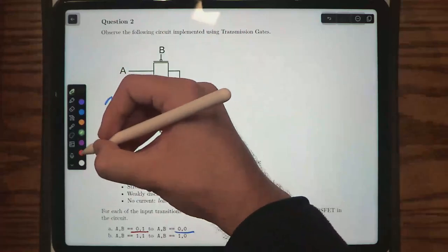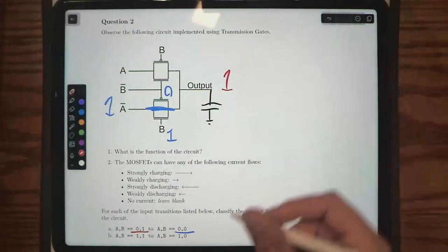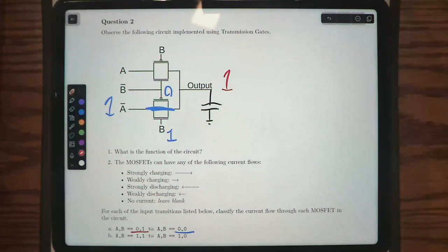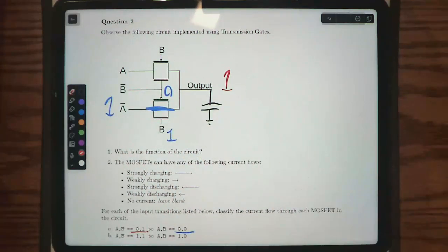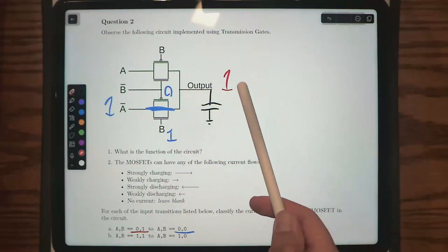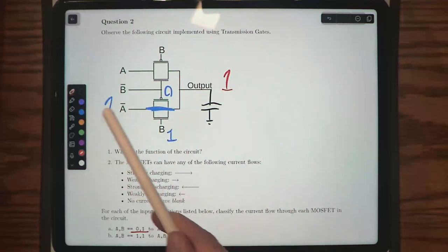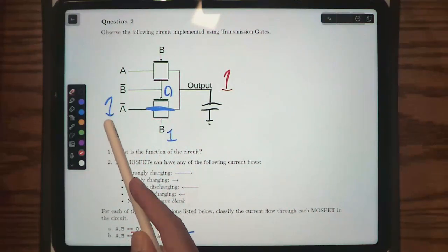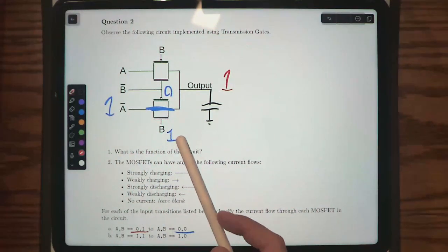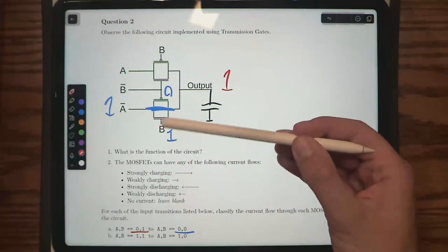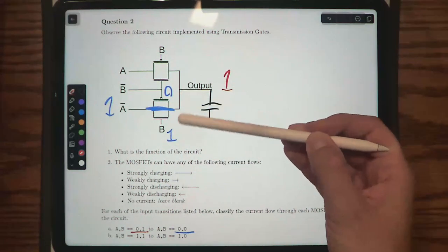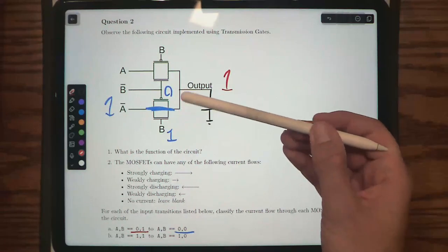And then maybe now we've switched, and now we have this case directly afterwards. So we've just switched from having 1 volt on the output here to now having these inputs. So we had A looks like a 0 and B is 1. So what current will now be flowing through these 2 transistors if we have this case?